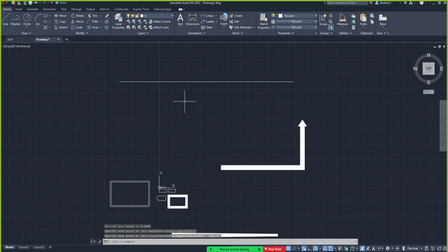If you were to practice that same thing from your own end, one funny thing about polyline is, if you use the starting width to be 20 and then the ending width to be 20, and immediately you stop or complete your design and then you want to use polyline again, it will remember that same width that you were working with, right? How do you reset it? You just simply enter the starting width to be 0 and then the ending width to be what? 0, and it will go back to the default.